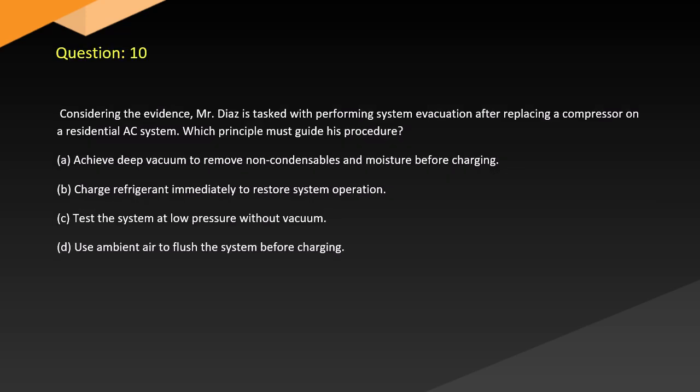Question 10. Mr. Dias is tasked with performing system evacuation after replacing a compressor on a residential AC system. Which principle must guide his procedure? A. Achieve deep vacuum to remove non-condensables and moisture before charging. B. Charge refrigerant immediately to restore system operation. C. Test the system at low pressure without vacuum. D. Use ambient air to flush the system before charging.